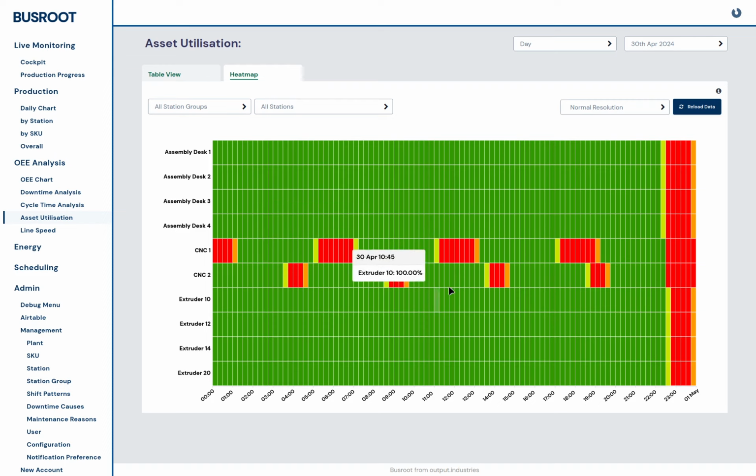And this is what we can see here, mocked up in CNC 1 and 2. In the case of a CNC, this is the way we operate with a lot of customers: we're monitoring the andon light of the machine, and the andon light generally links directly to whether that machine is actually being utilized, actually in operation. When the machine is being loaded or unloaded, the andon light is not green, it's red. And then only when the machine is actually running does it come up as green here, and that's what we're reflecting here.